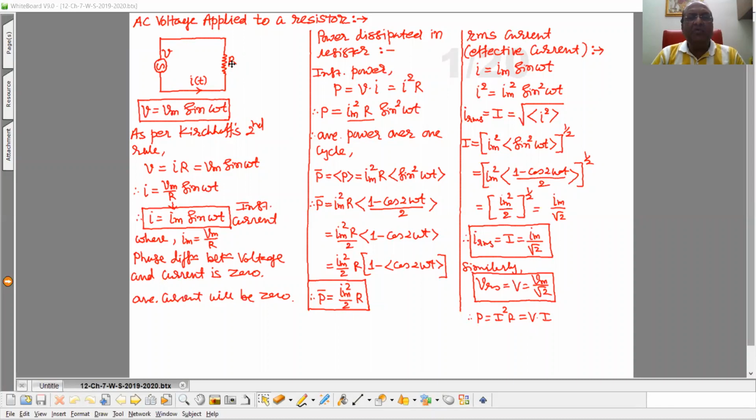Now this AC supply voltage is connected with resistance R. Suppose at a particular instant, the current in the circuit is I. Here be careful: whenever for any AC circuit you represent the current in the circuit, always represent time with it, because this is alternatively changing current, meaning the direction of the current is continuously changing as per the positive, negative half cycle of AC supply voltage.